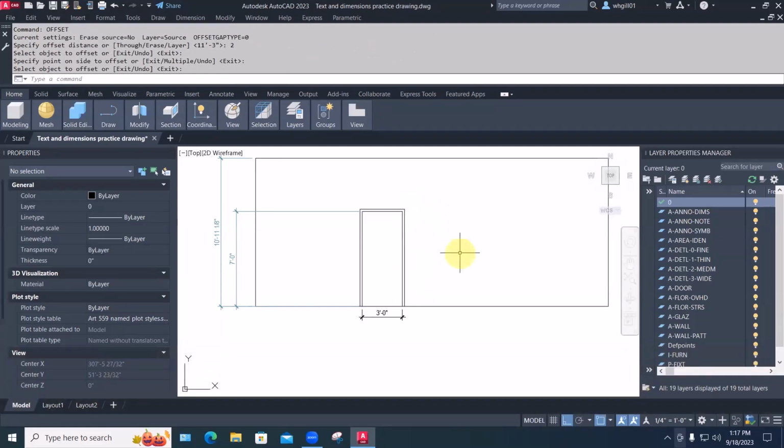And usually on your interior elevations, you won't end up dimensioning the door frames. There'll be a whole extra sheet somewhere, half a sheet or something maybe, with an elevation of the different frame types you're going to be using. And that would be 2 inches like this. Ones that go into masonry wall have a 4-inch head to fit into the concrete block module at 7'4". And wood ones will be 3 or 4 or 5 or 6 inches wide, depending. So you draw them here, but actually call them out specifically on another sheet of door and frame elevations.